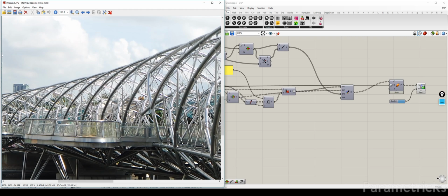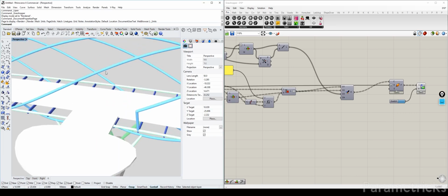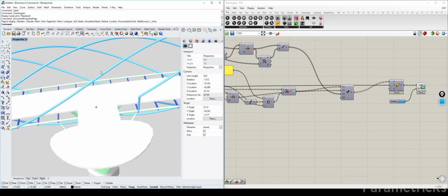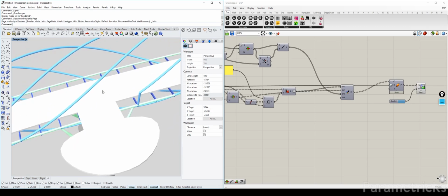So we need to find a third point, in our case the middle point, that will define that curvature, and the curvature actually follows the same circle that we used for our outer helices. So that's what we're going to do. But first, let's find that imaginary point that we need in order to define both lengths of that curved section.